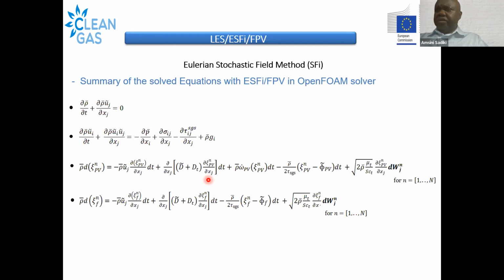It depends on configurations and on situations. So we'll show you some results for this single phase combustion, the turbulent combustion phase. If we have these stochastic fields, then we can obtain the mean value of the filtered quantities, the ensemble averaging through this n number of stochastic fields.